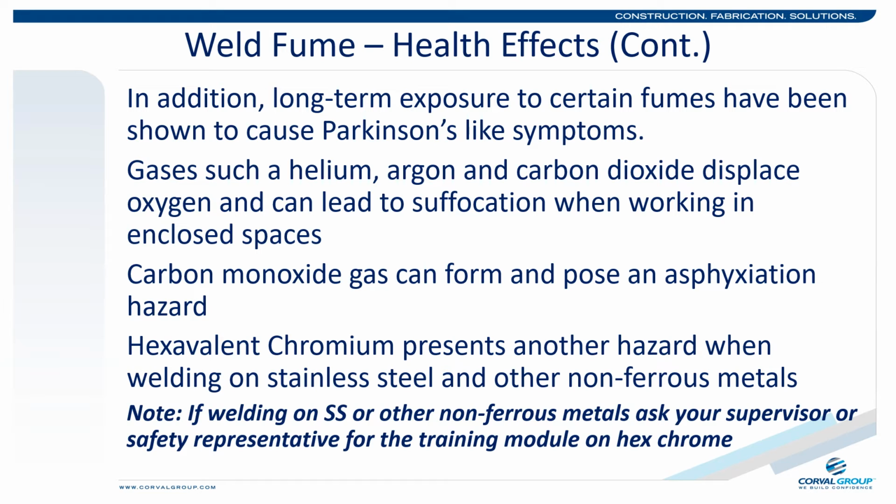Gases such as helium, argon, and carbon dioxide will displace oxygen and potentially lead to suffocation. Carbon monoxide gas can form as a result of the processes and pose an asphyxiation hazard. Should you be welding on stainless steel or other non-ferrous metals such as chrome or galvanized, ask your supervisor or safety rep to complete the just-in-time training module for hex chrome.